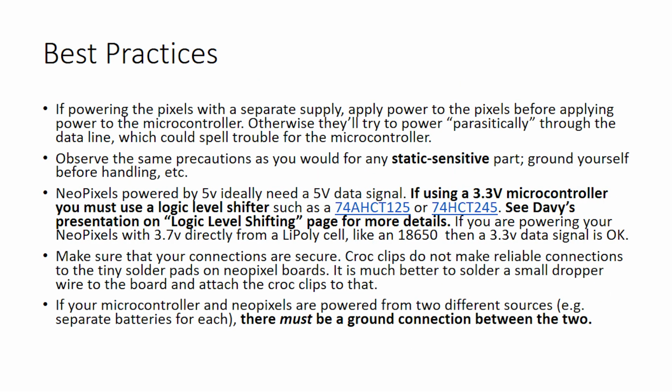They're static sensitive, so you've got to put your tinfoil hat on for them. My personal preference is my soldering iron is earthed via a 1 meg ohm resistor, and I use that. And as you know, I touch the soldering iron occasionally. The smell of chicken makes me feel comfortable and lets me know that I'm working properly, and that also earths my body down to the ground in the room.